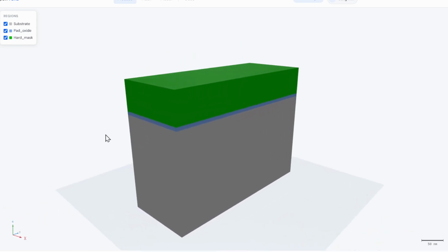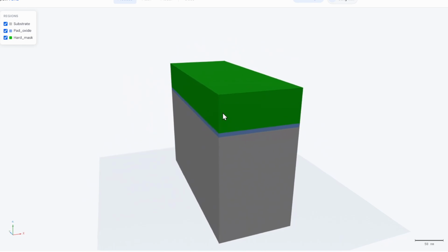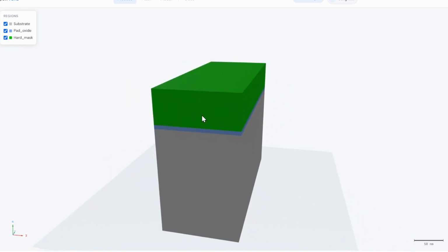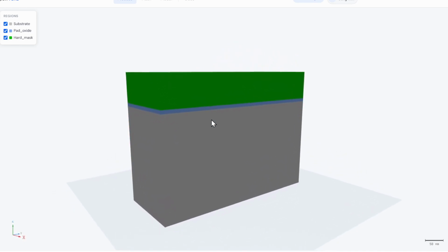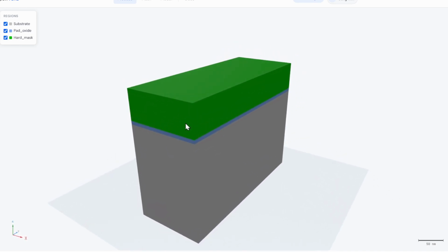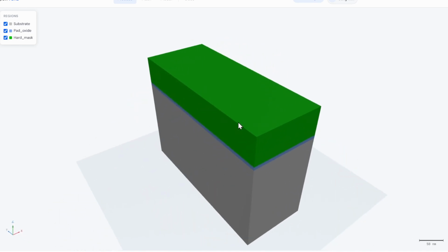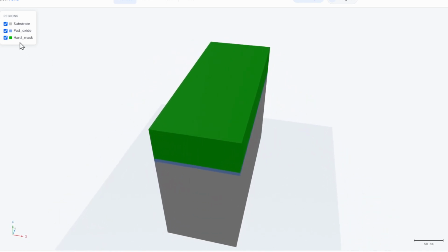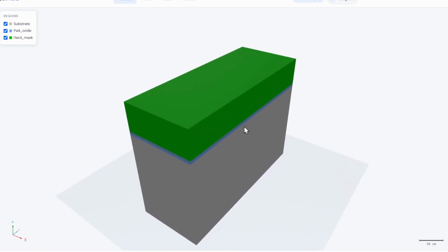Now we add this silicon nitride region called the hard mask. In this case, we don't have any patterning on it. It is just deposited globally, so now we have a very flat structure. Compared with the other material, this silicon nitride is regarded as a rigid one, so it is used as the so-called hard mask. Hard means that this can resist any kind of external damage.